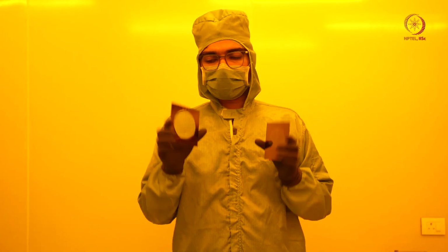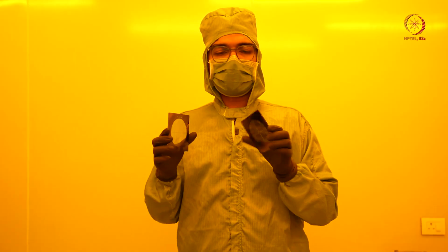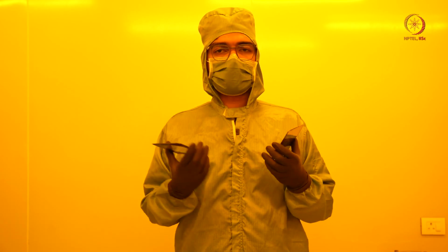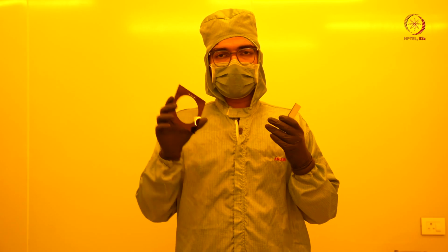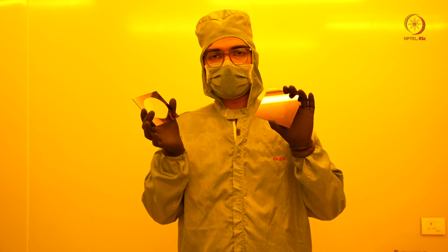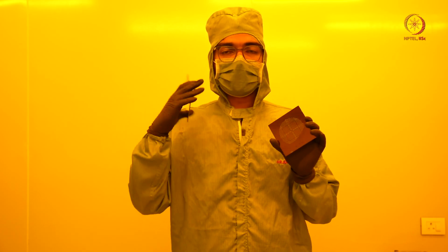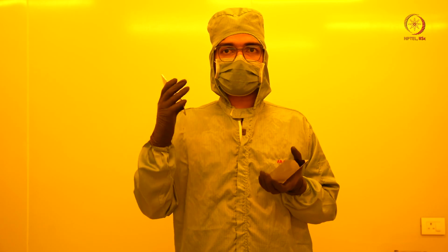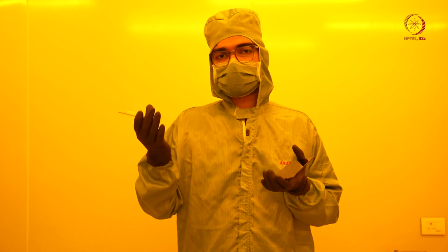All right, so we have seen a bright field mask and a dark field mask. Depending on the requirement that we have, we would change the mask. Now think about it like this: we have two different types of mask, bright field and dark field, and then we have two different types of photoresist, which can be positive or negative. So you can think of the possible combinations in which you can create a pattern onto the wafer or the substrate or the photoresist, right?